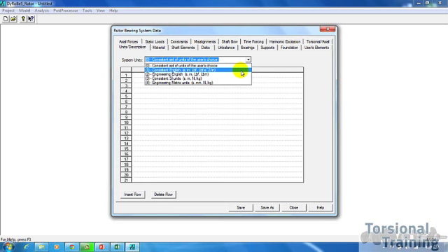One is the classic consistent English units, which is seconds, inches, pound force second square over inch. Engineering English, which is pound force and pound mass being the key differences, and then consistent SI units with meters and kilograms and newtons, and engineering metric units, which replaces meters with millimeters. Depending on what your preference is as far as units go, you can pick either of these options.